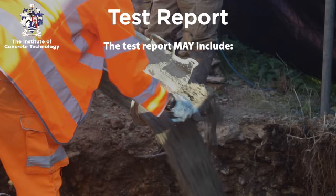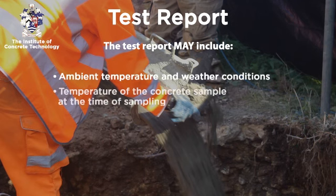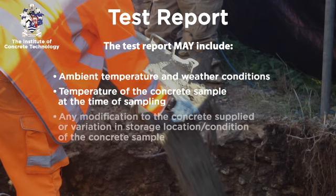The following information may also be reported on completion of sampling if requested. The ambient temperature and weather conditions. The temperature of the concrete sample at the time of sampling. Any modification to the concrete supplied or variation in storage location or condition of the concrete sample.